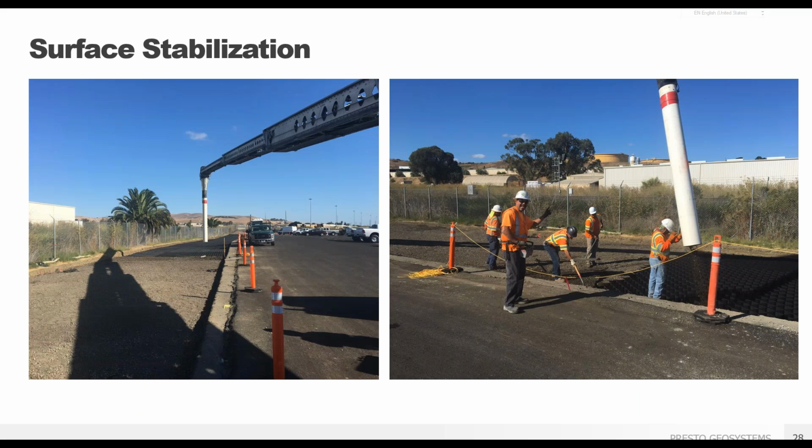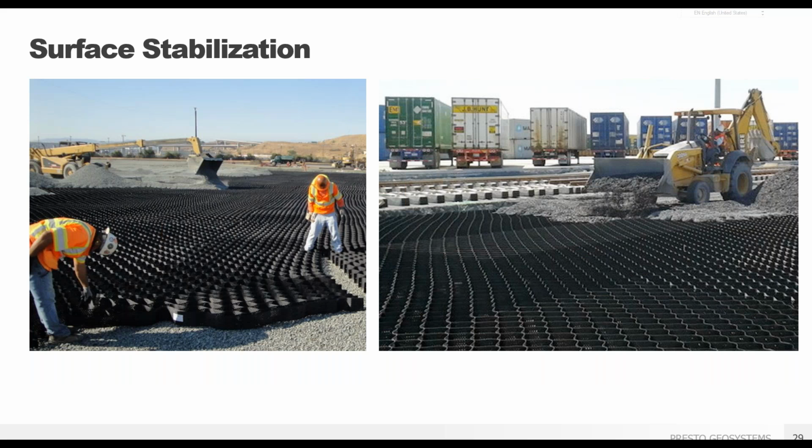There are many ways to place the infill. A rock slinger is one of them and allows precise placement for fast, even filling, while controlling the height from which the aggregate falls. Buckets with extendable booms can also be helpful, though a push with a dozer or backhoe will work just fine.